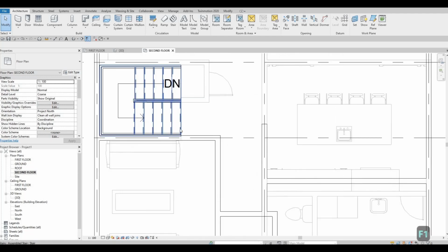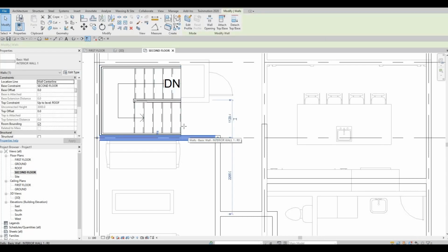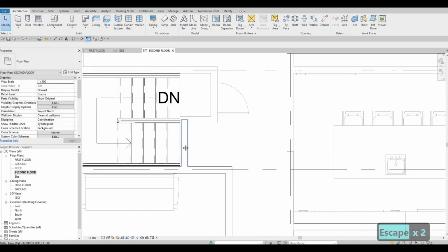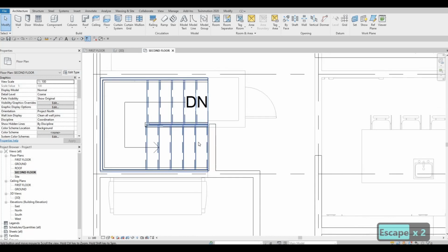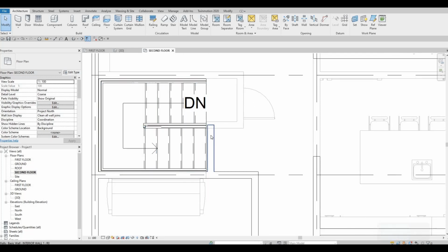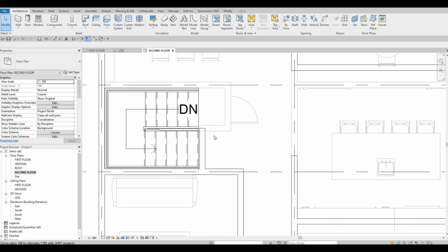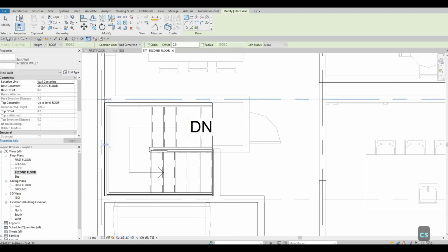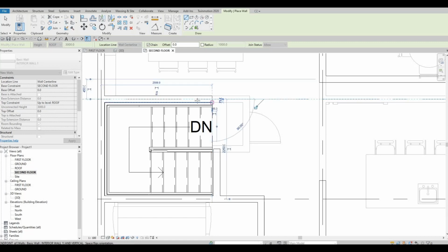And then now we need to close this wall or this stairs. So select this interior wall, CS, and we just need to add a wall right here because that's going down. Instead of adding railing, we could just add this one, or we could add railing if you guys want. It's up to you. You just need to close those off. And then here, select this one, add a wall right here. So just completing that.